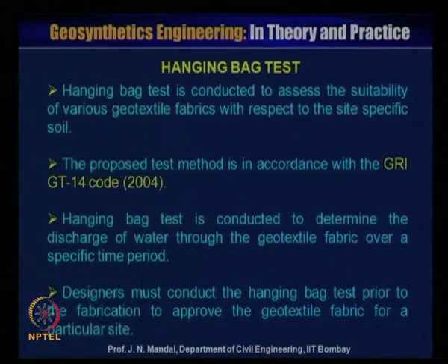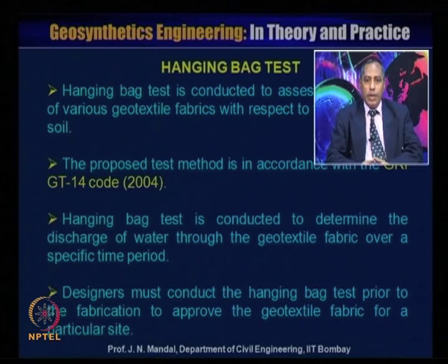The hanging bag test is conducted to assess the suitability of various geotextile fabrics with respect to site specific soil. The proposed test method is in accordance with the GRI GT 14 code of 2004. The hanging bag test is conducted to determine the discharge of water through the geotextile fabric over a specific time period.